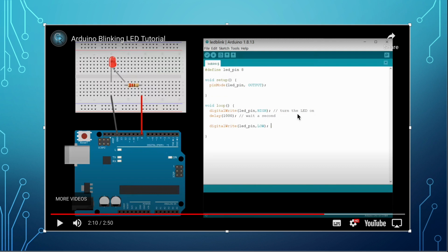As the code reads, now it is high, that means the bulb is switched on. It will stay on high, so there is a delay happening, it will stay here until 1000, let's say for our benefit 1000 milliseconds, has been reached to go to the next step.